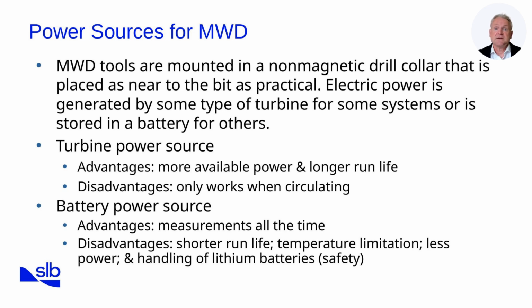Battery-powered systems, typically lithium-based, enable continuous measurement whether circulation is active or not. This is especially useful for capturing data during static conditions. However, batteries come with challenges: limited run life, sensitivity to high temperatures, reduced power capacity, and safety concerns in handling. Additionally, the batteries must be disposed of in an environmentally friendly manner. Currently, there are only a limited number of processing facilities worldwide.